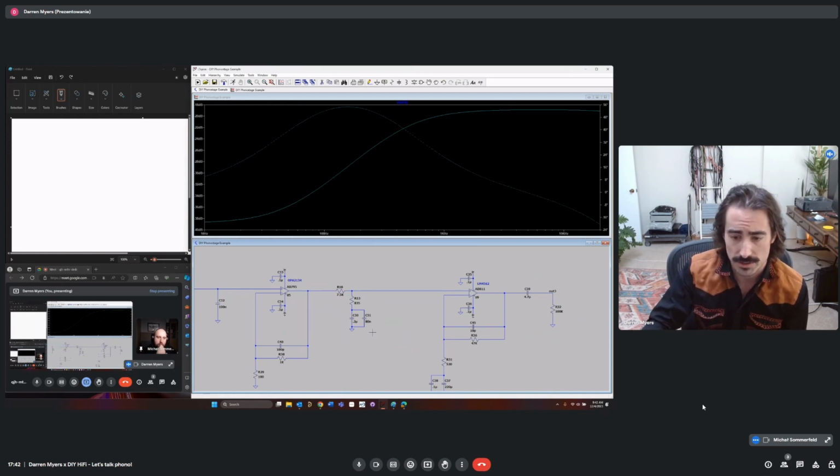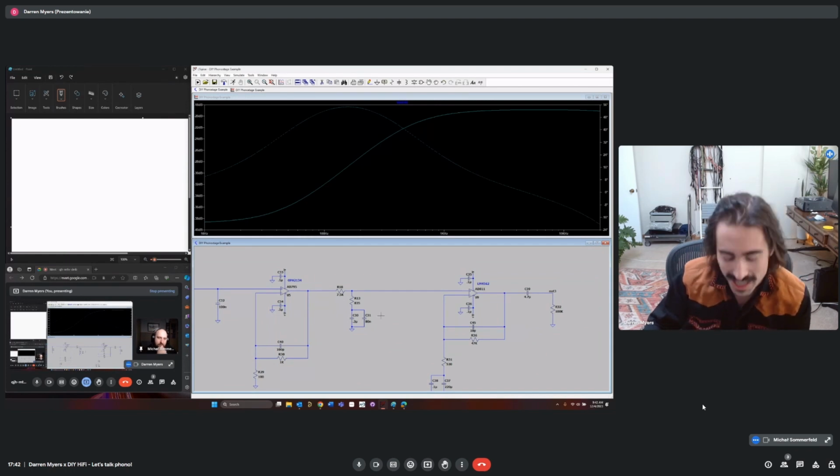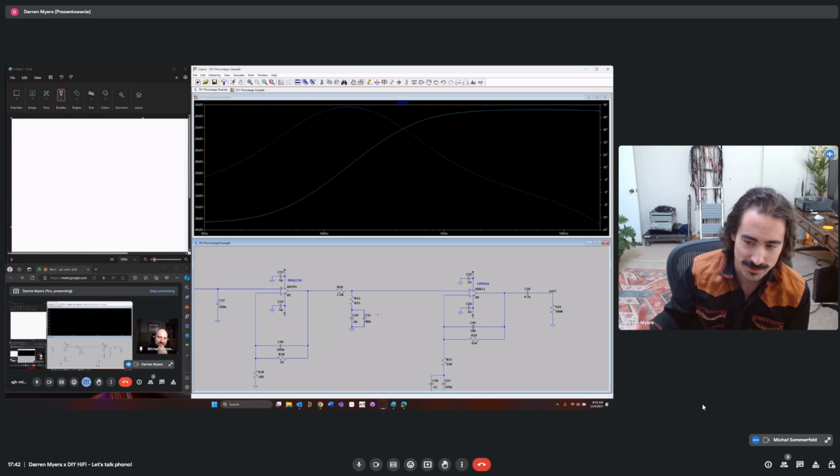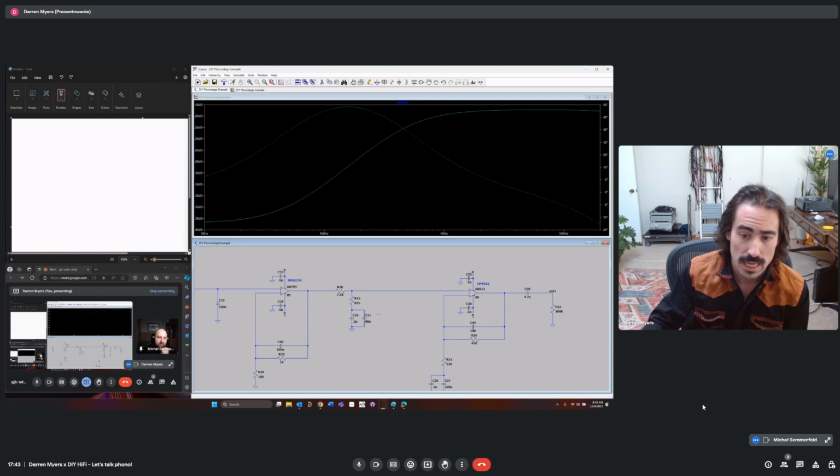And then we're going to have our 318 microsecond pole and our 3,180 microsecond pole. I apologize, I misspoke. The 500 hertz and the 50 hertz pole, and so our two time constants at 318 microseconds and at 3,180 microseconds are applied right here.